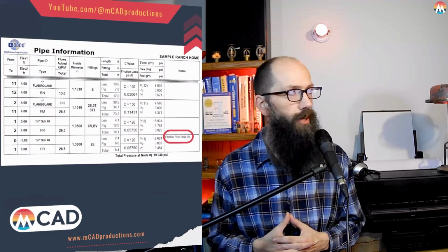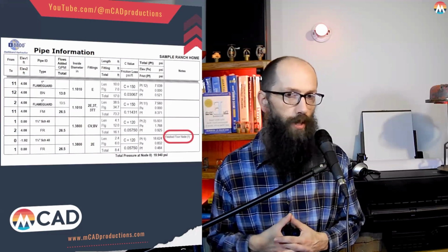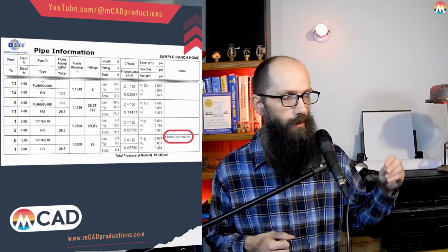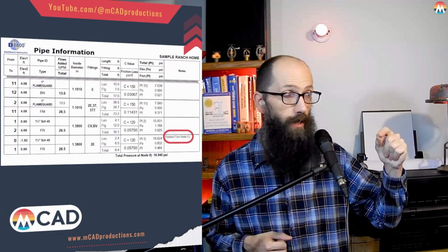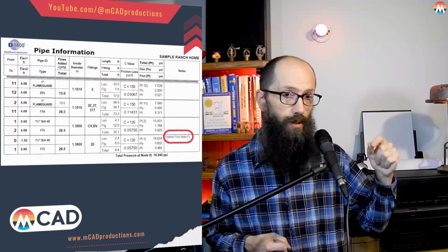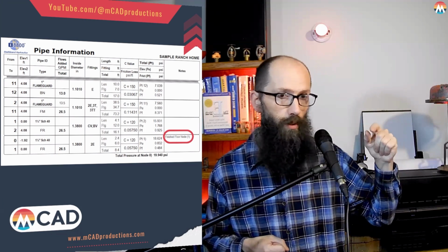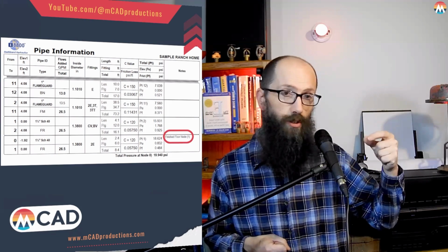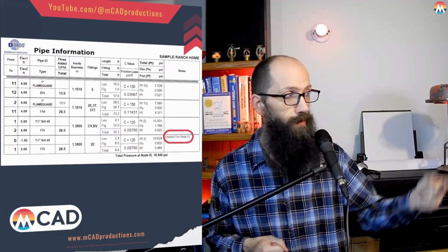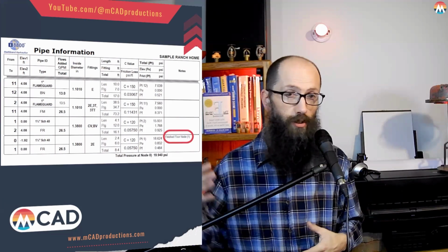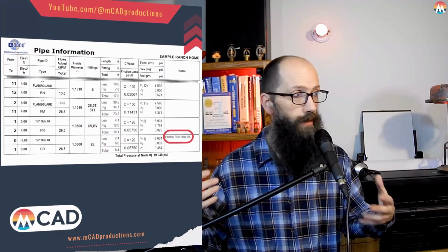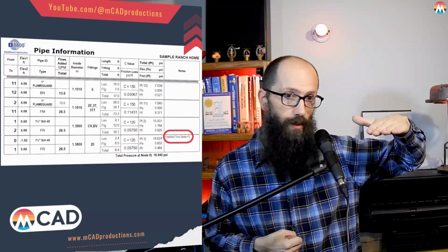This is part of why, I don't know if you saw in the elevations, it went from negative 1.92 to 0. It's because I set node 1 as the finished floor to show you what it does. Whatever node is your base of the riser, you put that, and then it sets that as 0.